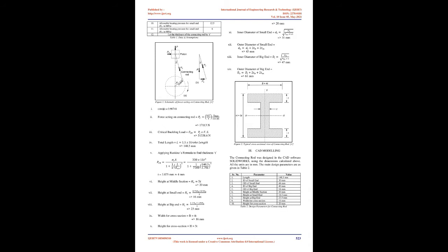The connecting rod is generally made from materials like medium carbon steels or alloy steels. The carbon content varies from 0.35 to 0.45% in medium carbon steels. Typically, nickel chromium or chromium molybdenum steels are used as alloy steels. The connecting rod is usually manufactured by the drop forging process, casting process, and powder metallurgy.